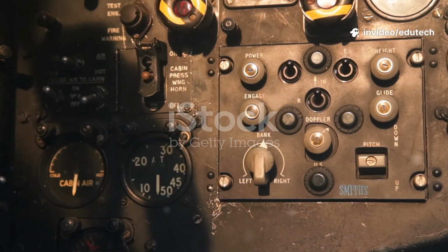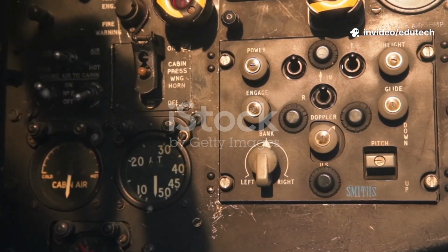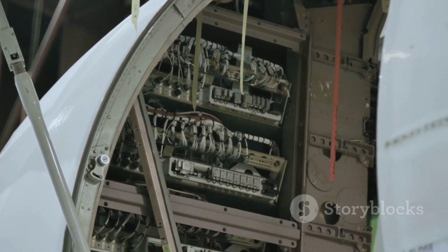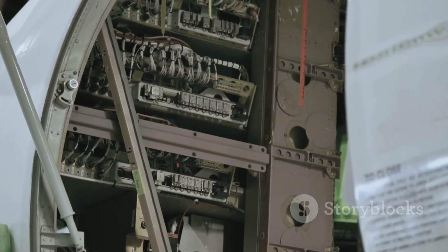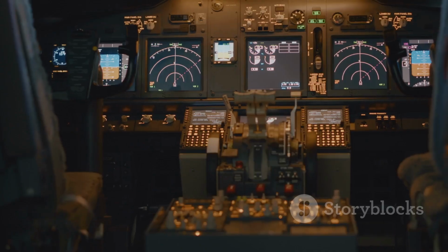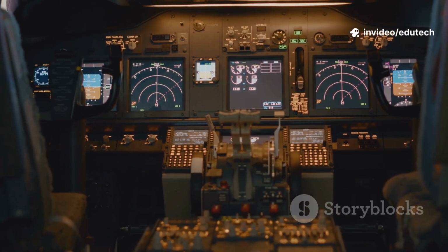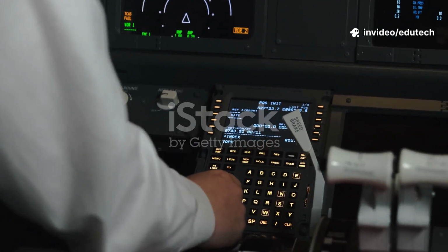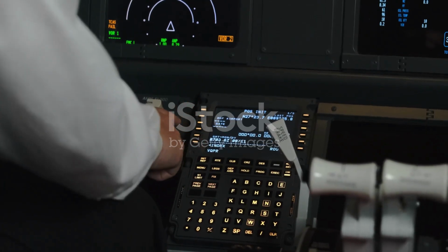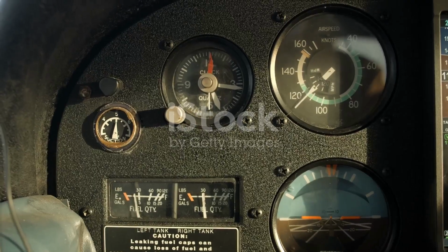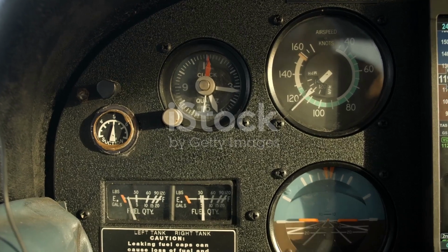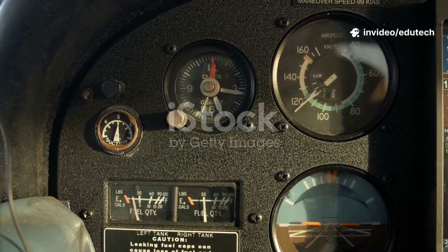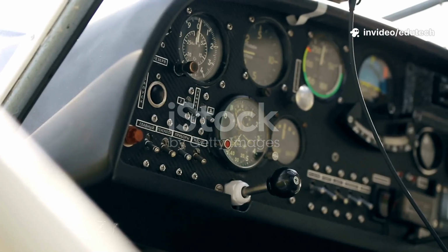Original analog flight instruments are operated by air pressure and the use of gyroscopes. This avoids the use of electricity, which could put the pilot in a dangerous situation if the aircraft lost electrical power. Development of sensing and display techniques combined with advanced aircraft electrical systems has made it possible for reliable primary and secondary instrument systems that are electrically operated. Nonetheless, often a pneumatic altimeter, a gyro artificial horizon, and a magnetic direction indicator are retained somewhere in the instrument panel for redundancy.